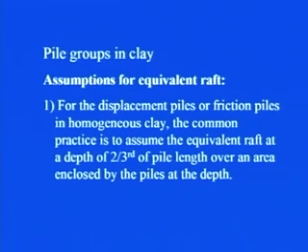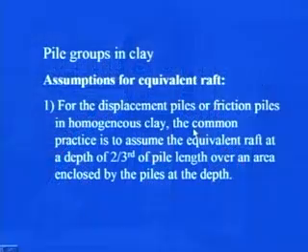So, when a pile group is there, on top of that you connect all the piles and that forms a pile cap. The size of the pile cap depends on the extent of the area over which the piles have been spread. In that case, whatever is the area covered by the pile group, we place the raft of the same size at a depth of 2/3 of the pile length over that particular area.